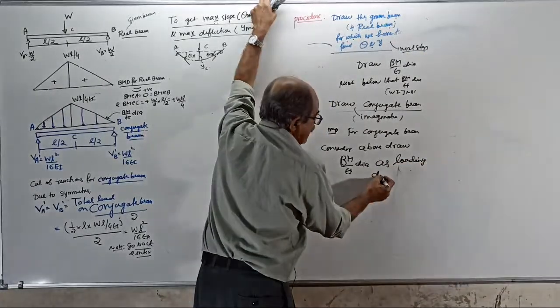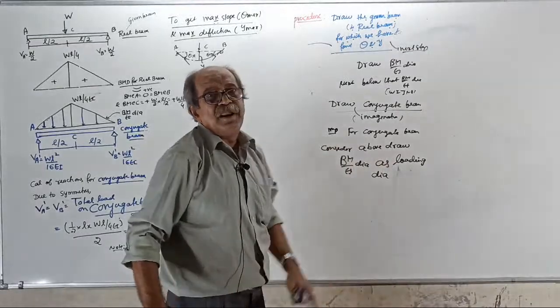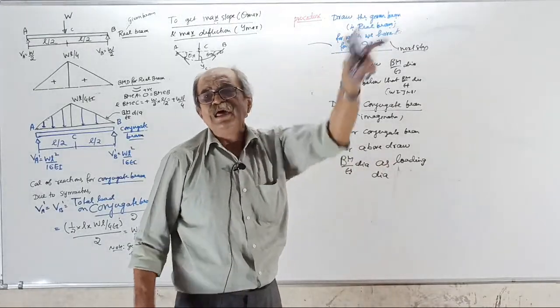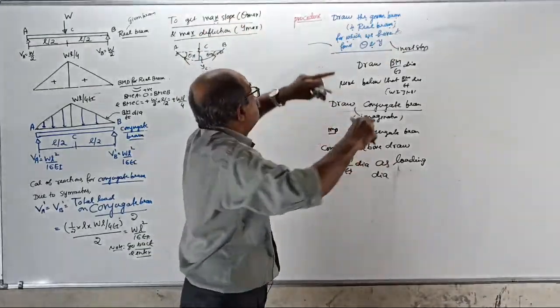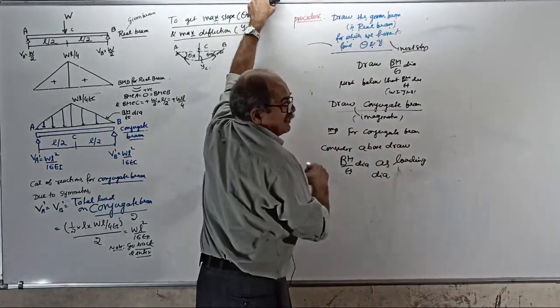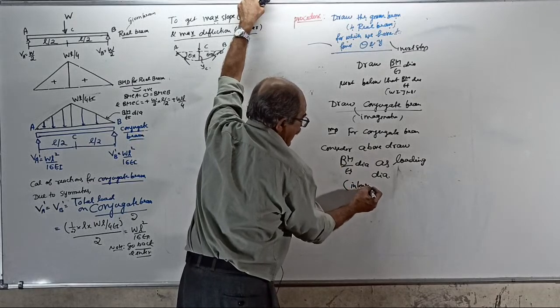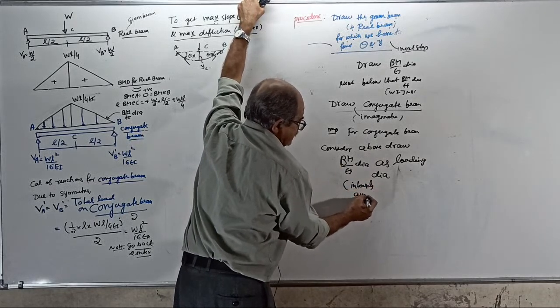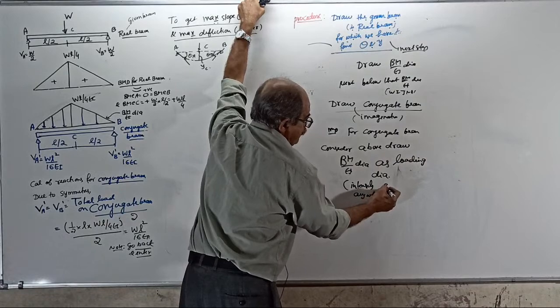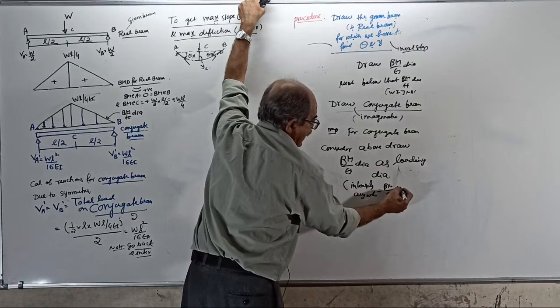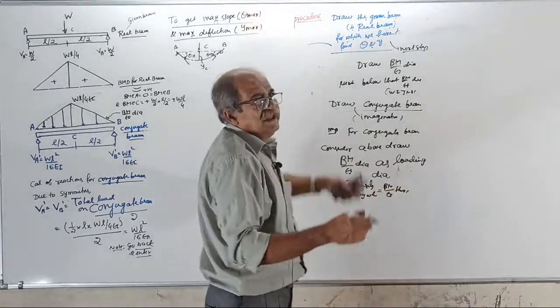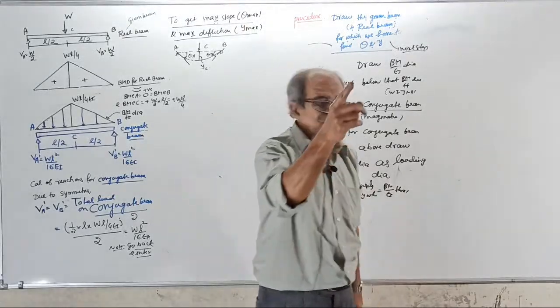Oh, one thing I forgot. I will tell it now, one important concept forgotten. You add the principle. See that box? I forgot the loading diagram. Okay, remember, intensity anywhere is equal to what? BM by EI there. Correct? Anywhere you want intensity, it is BM by EI there.